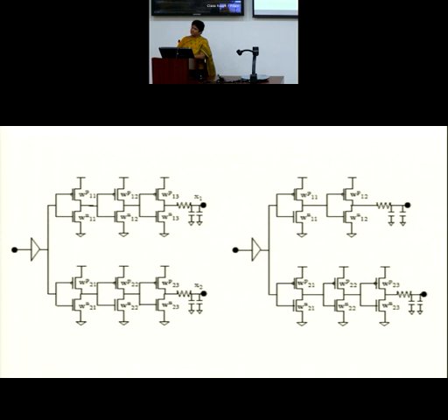Now you can take any example. Suppose there are two paths from source to destination. Purposely I am taking two equal paths so that wire segment delays are not affecting. What is coming in the skew variation is because of the buffer or device mismatch. So three buffers in this path and here also three buffers in the path. Source S0 to X1 or S0 to X2 also has three buffers. Now it can have two buffers also, four buffers also. It is immaterial. We have to look at the strategy.